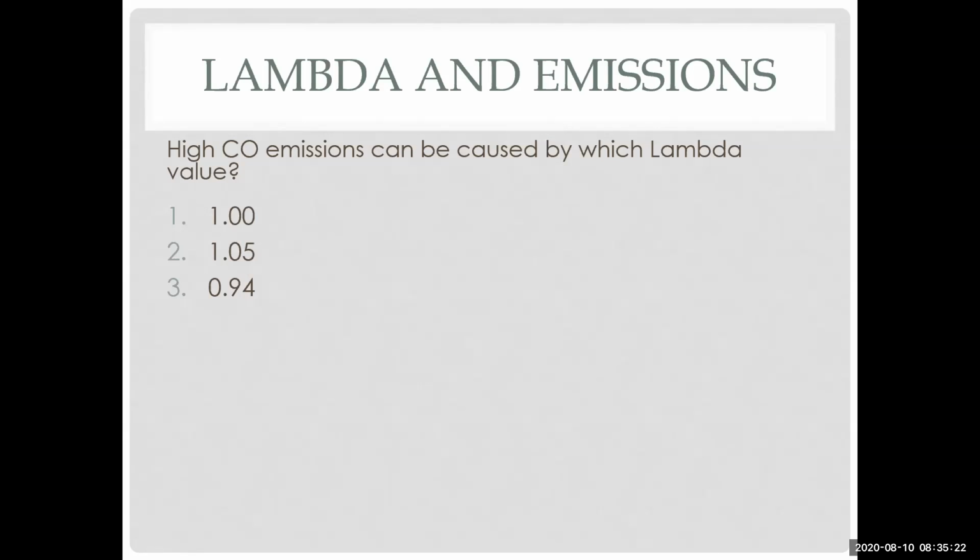What we're getting here is the result coming out now. This is what happens if the car was running at possibly a 0.94 lambda. This is where emissions would go up. So CO will go up at that, just like NOx will go up at 1.05 lambda or 1.04 lambda. Can the car handle that? It depends on the car.